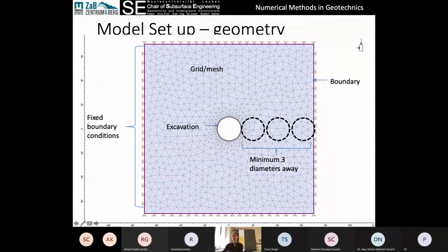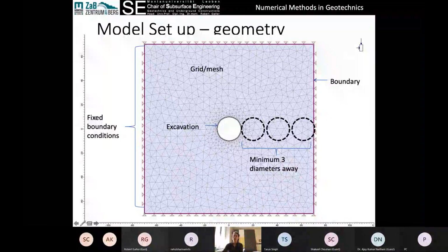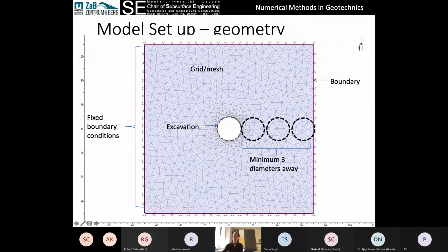There's a mathematical solution here, which is fine, but it's not a true solution as though there was a material here. And so oftentimes corners will be a little bit funny, so we want the corners to be as far away as possible from our area of interest. We're trying to solve for what's happening in here. We don't want our solution in here to be affected by the funny things that are happening in here.